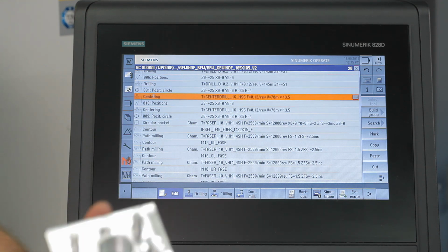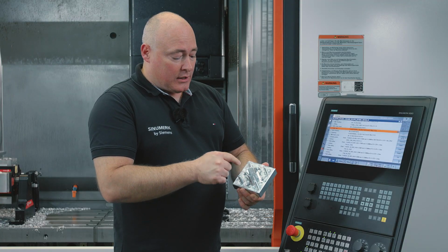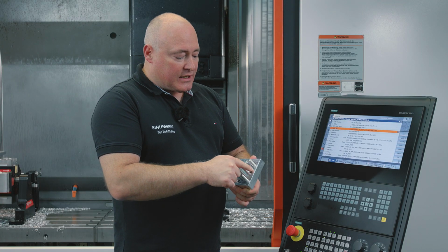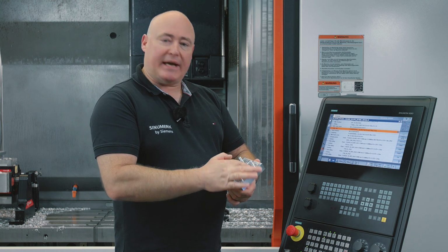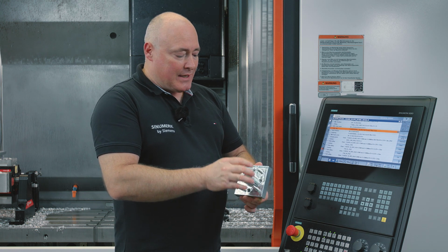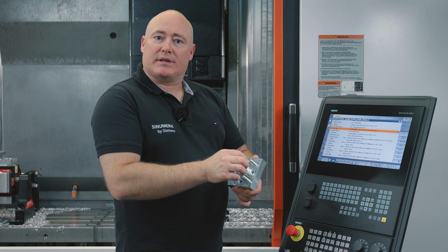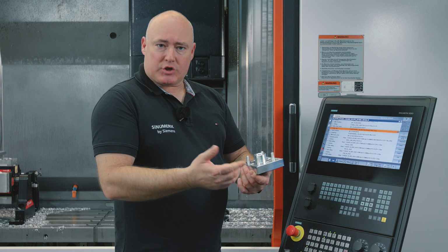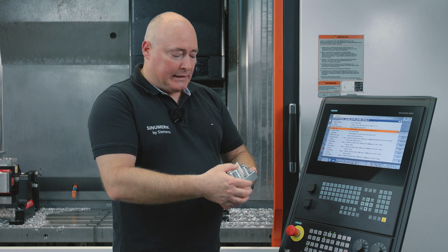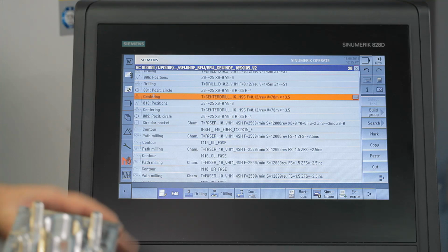After drilling, we must chamfer the tap hole diameters, because the thread chamfer protects the future thread so that the first thread is not damaged and the mating part can be screwed in correctly. It also removes any burrs, because sharp edges are created when cutting metal, which are then removed in the process.